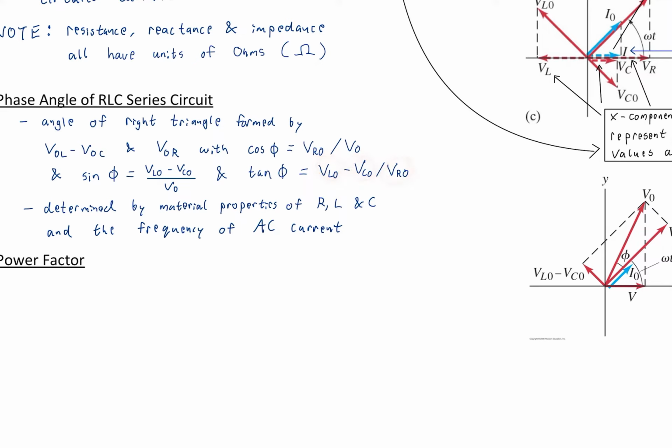Inductance is determined by the number of coils and the diameter, capacitance is determined by the plate area and the separation distance and whether there's a dielectric, resistance is just determined by the length of the wire and the diameter of the wire, and reactance of capacitors and inductors are frequency dependent. So that's everything that goes in. And if you know all that, then you know your impedance, you know the overall effect on the current, and thus you know the phase angle, and the power.